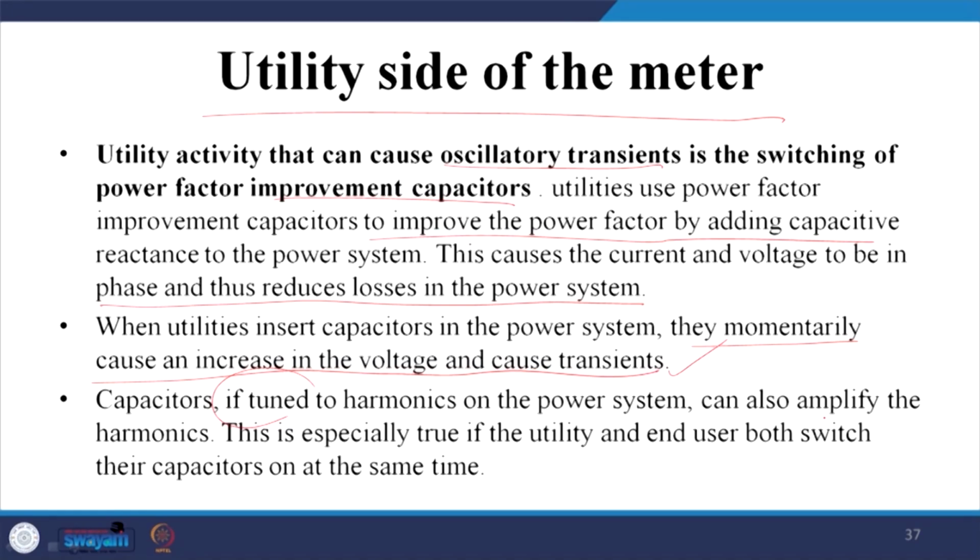One of the major disadvantages of the passive filter is that if it is tuned to a particular harmonic, it may cause a resonance, with the leakage inductance and this capacitor bank, and that sets up the resonance, and it is aggravated by the presence of that particular harmonic which you want to attenuate.